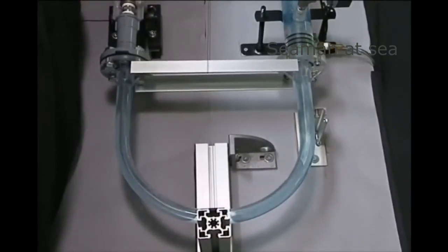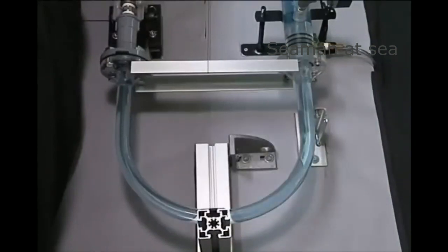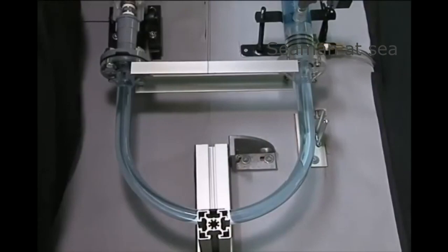The U-tube is movable. When pushed by the water force, it moves back and absorbs the impact. With an actual pipeline, such impact cannot be absorbed fully, resulting in damages such as cracks. Damage to the dresser joint is typical. Now we'll review this process using an image simultaneously shot from 3 directions.